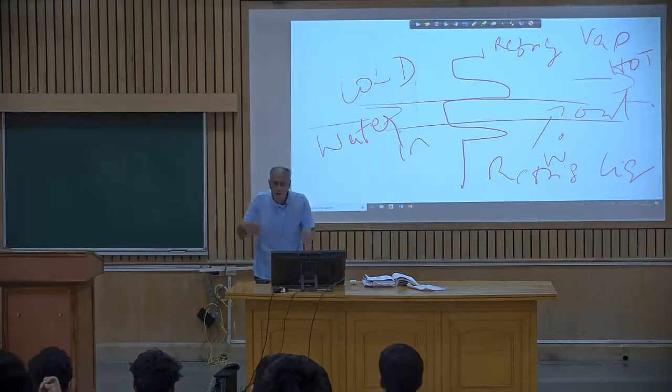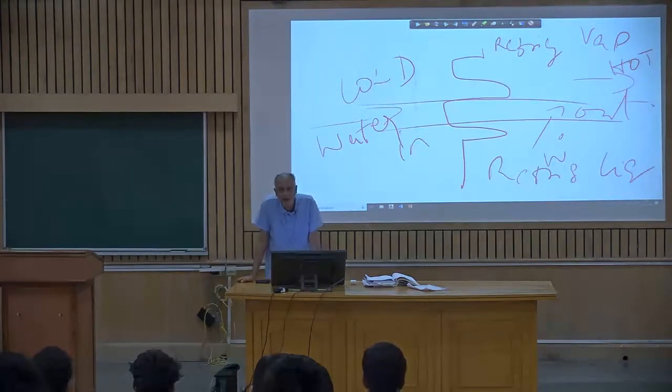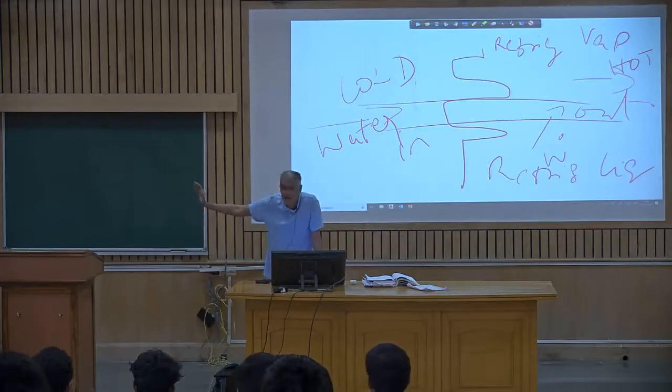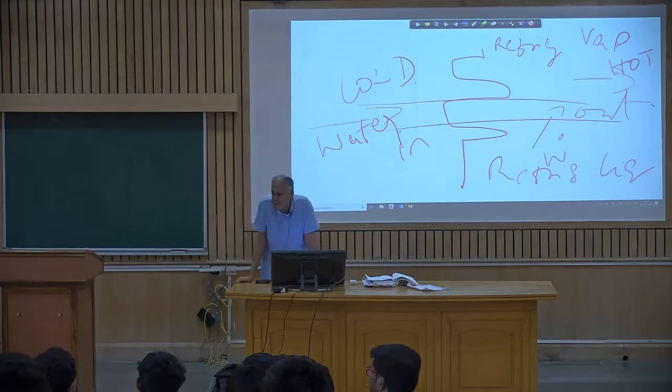The jet will not have time to adjust to the area changes. Got it? It will go hit the boundary and it will get accumulated and start rotating right there. It will lose its energy. So all your design, the edges and the corners, you have to keep gradual changes in dimensions for a reason. Otherwise, you will have stress concentration there. That's why if you see most of the designs, you will have a curvature there. Nobody should have a sharp corner.